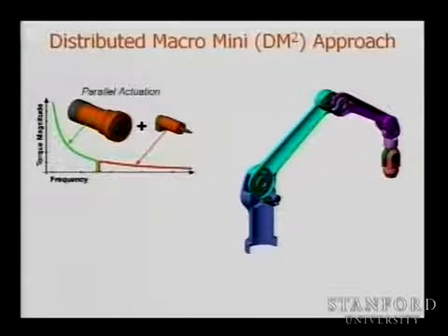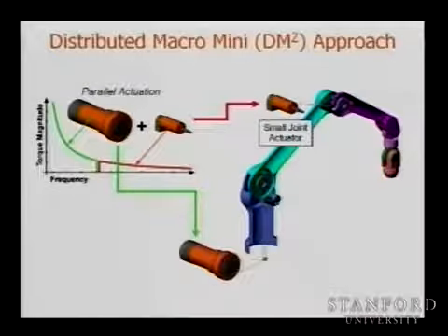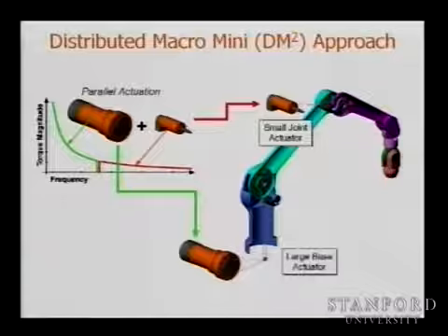We never think about it, but we can design the robot not with one motor, but with multiple motors for each joint, like humans have multiple muscles actuating, and actually different types of muscles. So you can place a small motor, the structure will be light, very safe, and you put a big motor at the base. You remove the weight.